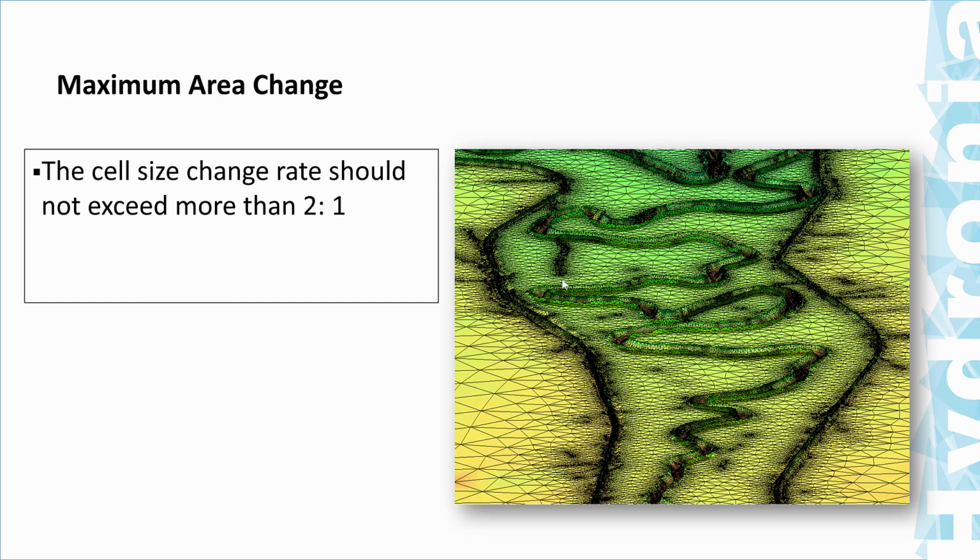Now, we'll see that the mesh, as we said, is formed by triangles, but you can refine the mesh in many different ways. So if you have a channel or a main channel in the river, you have tools to make the mesh within this channel much denser.